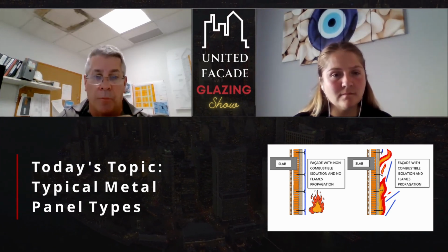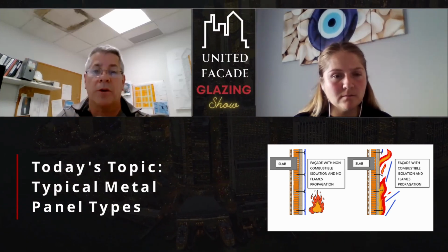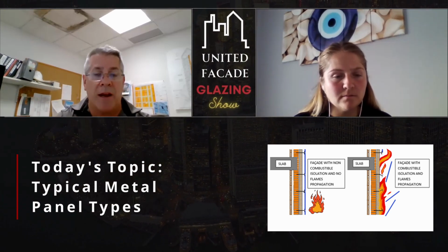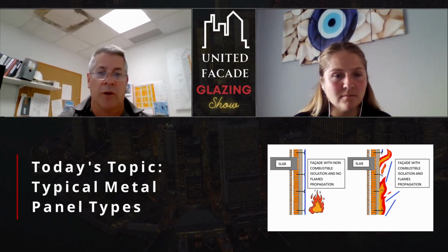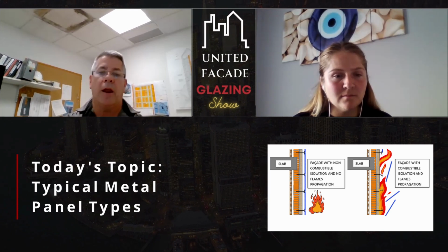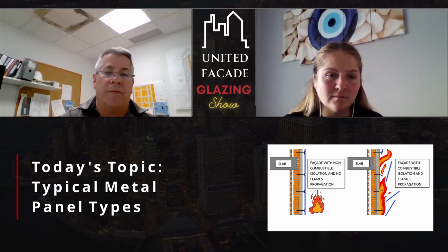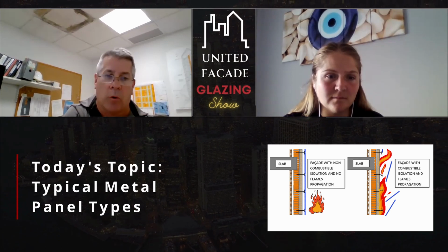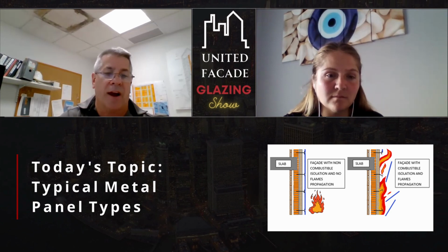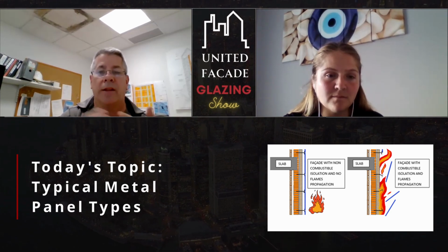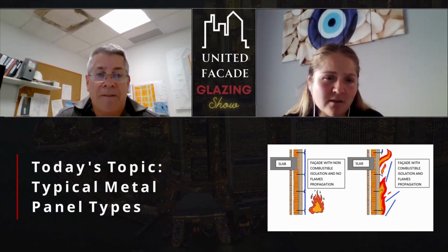So if you're on a commercial building, you say, okay, I can tell right off the bat, yes, that's the FR core because it's this color. And each manufacturer might have a different color. So I can't just give you a general say one is black and one is white, but it's almost as simple as that. So if you have manufacturer A, their FR core is one color and their PE core is a different color. Same with manufacturer B, they may have one color and a different color for each of the cores. So we can divide them from their colors?